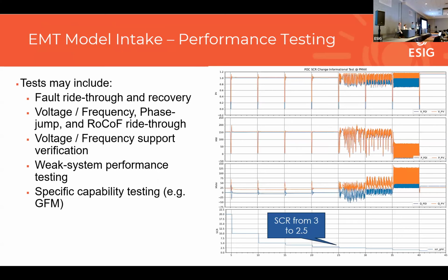So within this performance testing space, there are specific things that we will look for, and I mentioned some of these already. Things like fault ride-through and recovery, we can keep a close eye on that. We can do balanced and unbalanced faults of varying durations. Another thing we can do is voltage and frequency ride-through by playing in a certain curve, like your PRC-024 curve, for example.